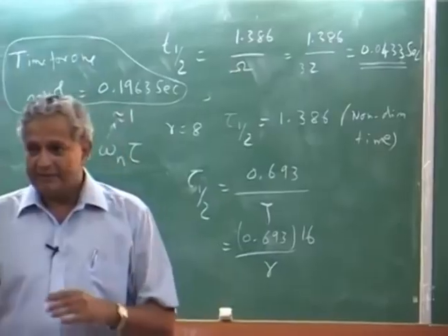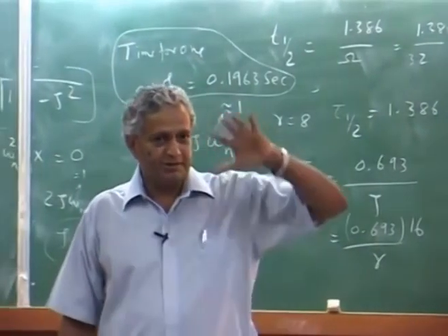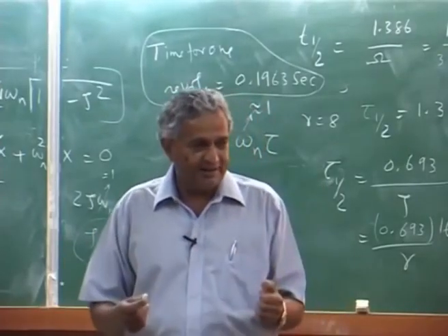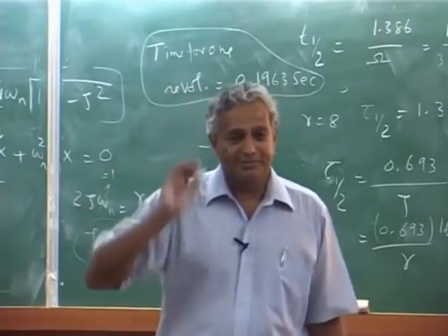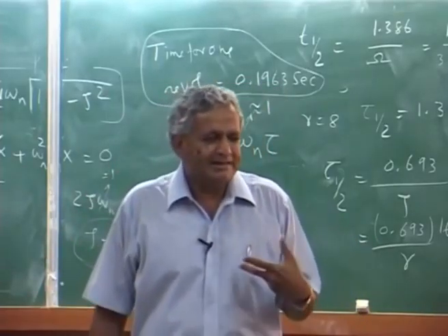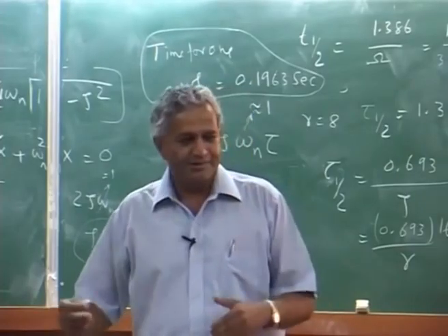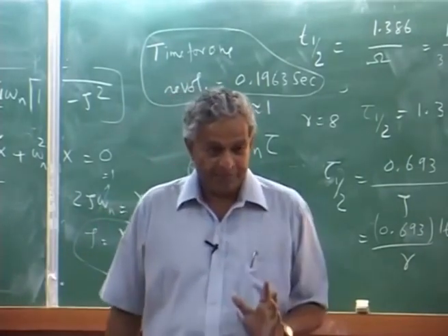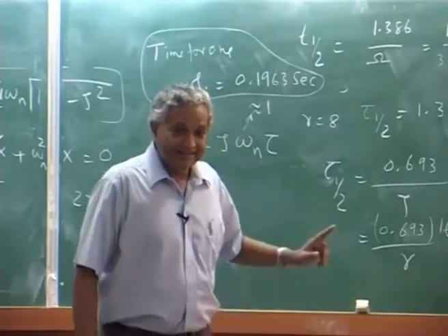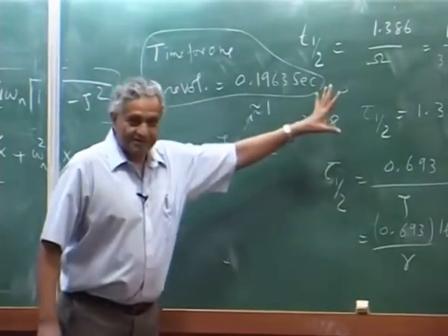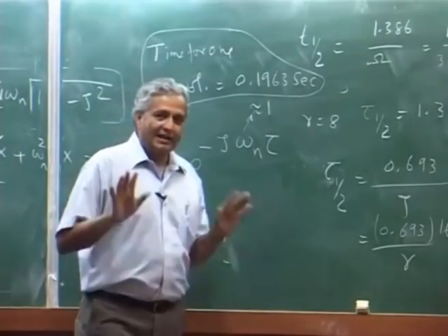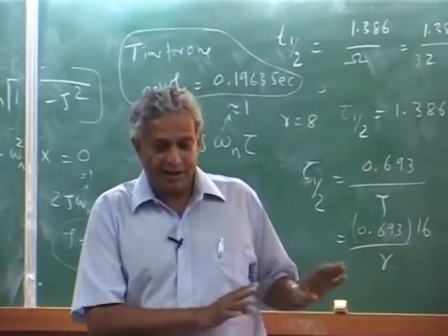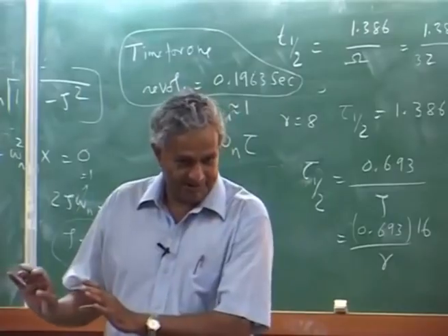That is why when the pilot gives any input, the response of the flap is quick. He won't recognize or feel a delay in the response of the blade. You can take it as though input and output are instantaneous, even though there is a slight delay, but you neglect that delay. Why this is important is that this particular number lets me make an approximation, which is called the quasi static approximation.